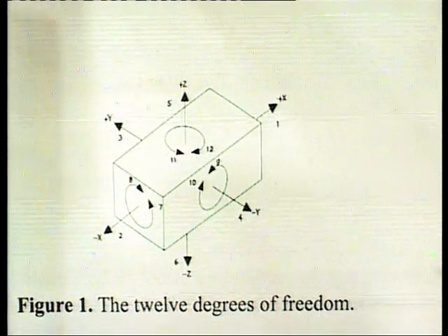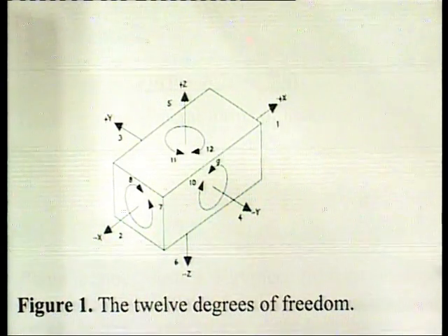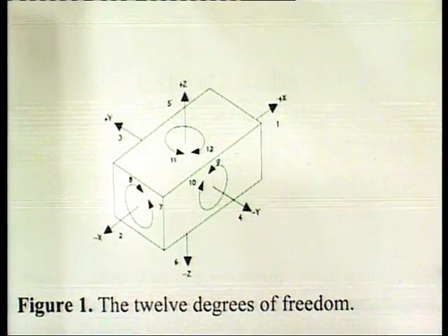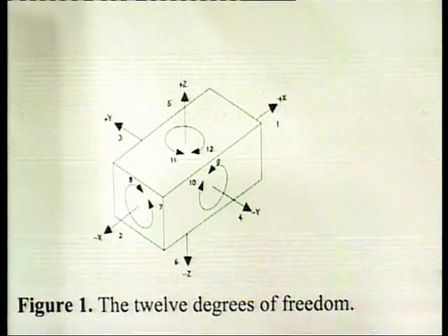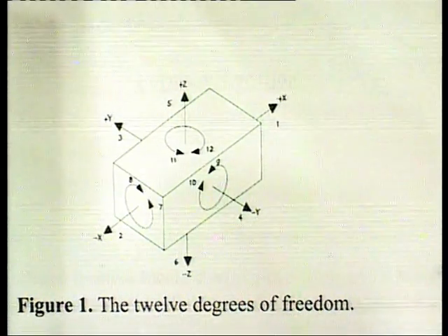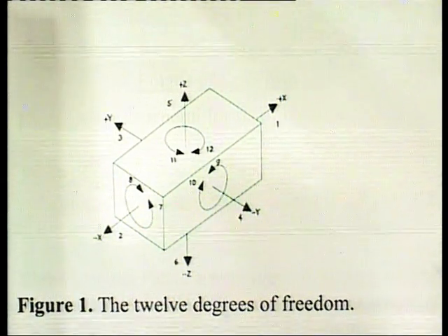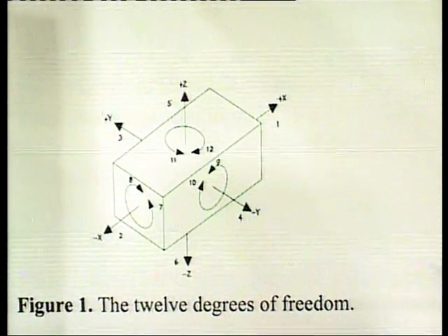The workpiece cannot move. Clamps, on the other hand, rely only upon friction between the clamp and the clamped surface to hold the workpiece. Sufficient force could move the workpiece. Clamps are only intended to hold the workpiece against these locators.